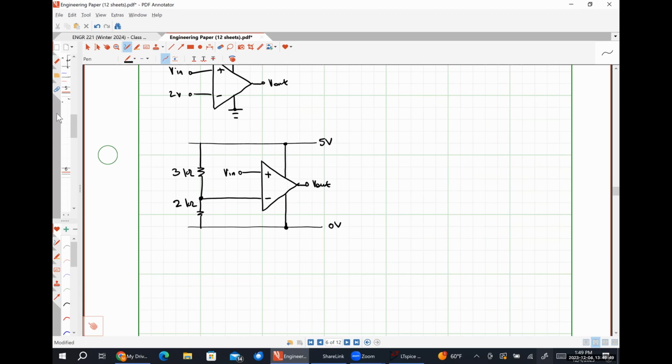There's no closed current carrying loop. Right, so the current is 0, the voltage drop across the side is 0. So for the open loop, you just want to do the voltage. But also for the source transformation, does it matter if you put the voltage source on this side and the resistor on this side? Not at all.